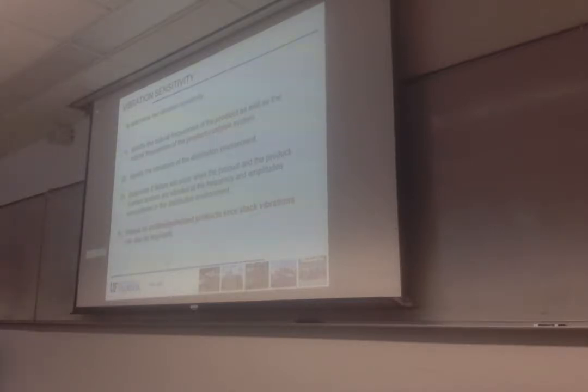So first, if you have a product with many components, obviously if you have clothing, it's useless. You don't need to do that, okay? But if you have a product with many moving parts, components that can move freely, things like this, you should first attach the product to the vibration table. That means you fix it on there so it doesn't move, and you shake it, and then you look at whether you get any resonance from any of its components.